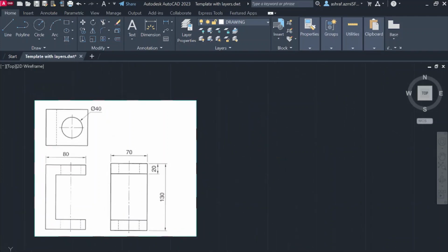When you are drawing on the top, make sure you change the isoplane to top. You can see this. How can you change it? Just by clicking F5. So this is your isoplane right, and this is isoplane left. You are going to draw the top first, so select isoplane top.